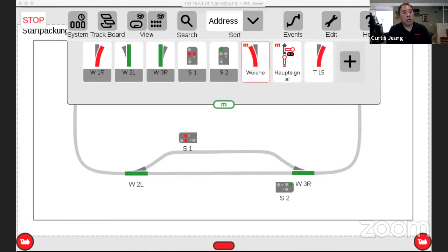And so let me begin with the adding of a multi-decoder. So there's probably going to be a little bit of a difference between, I guess we can unshare your screen right now. So this is a newer style M83. It's got screw terminals on it. It's a 4-gang box. So basically what happens is that when you address the number 1 address, it's going to reserve the next 3 addresses. And as you can see here at the top, there are dip switch settings here.